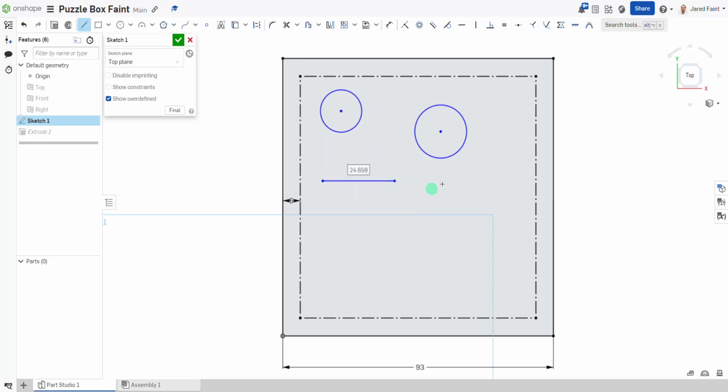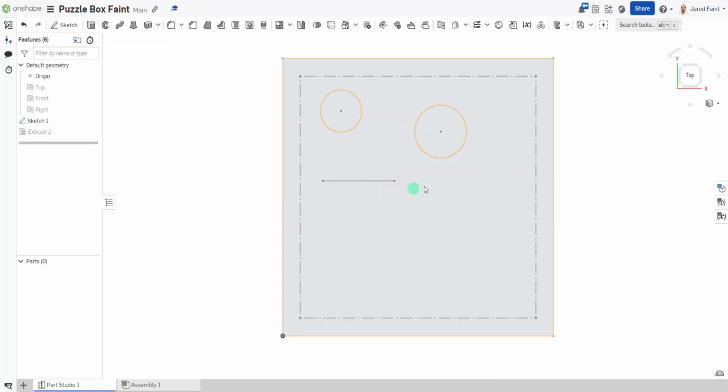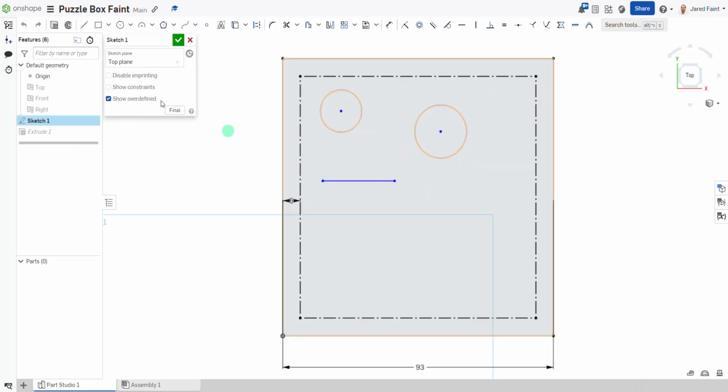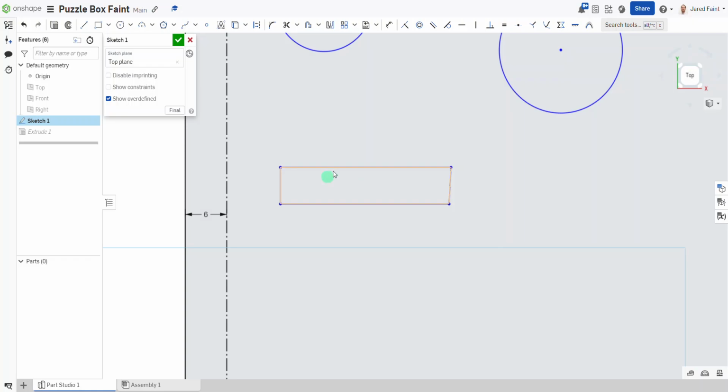That's not going to do anything, because if I exit that sketch, that doesn't do anything to it. So if I want to be able to have a line through there, I need to make sure that there's some depth. So I'm going to drop those in through there. Now, there's a few things I can do to that line now. So at the moment, those two, I might want to be parallel, which is then going to square those up. Those two are already horizontal, which is okay, so I can make them parallel as well.